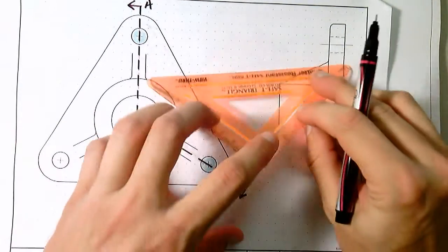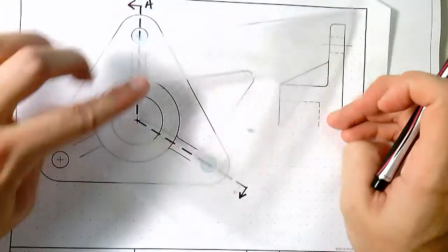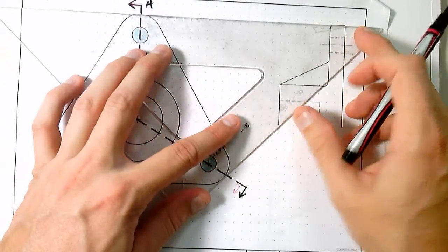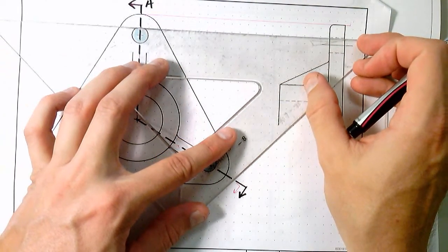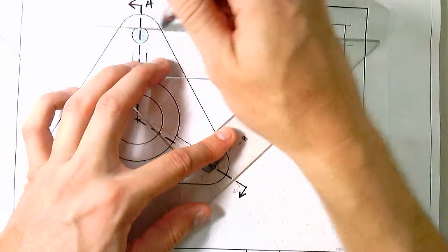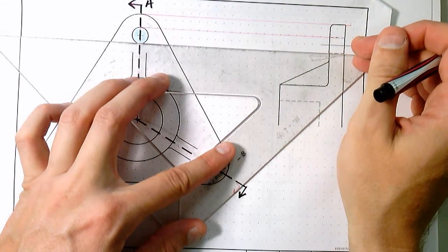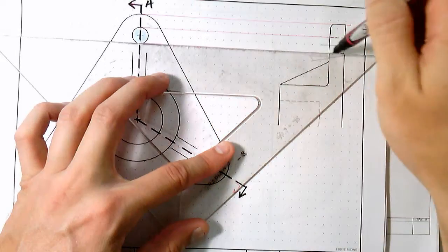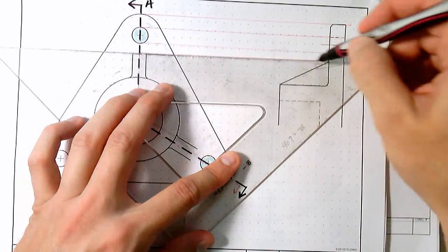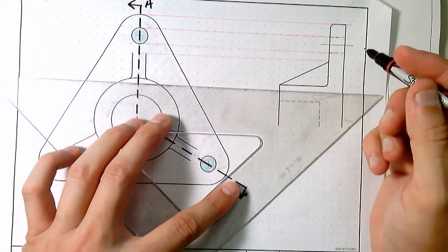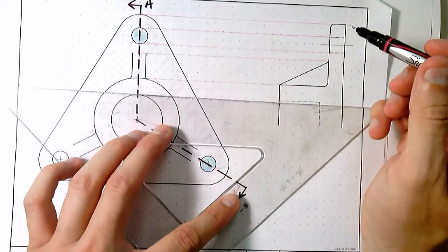So the first thing we're going to do is check and align our projection lines, make sure everything's square. Notice you should be using a straight edge to get clean, crisp lines. When you're doing projection lines, you're going to be using a light 2H or a 4H. Here's a rib or a web. This will become important in a little bit. Notice we won't be cutting through that because it's cutting with the direction of the rib.